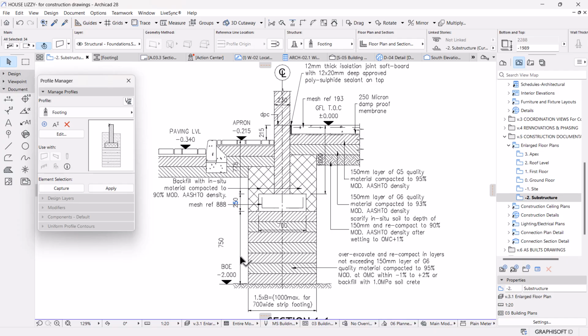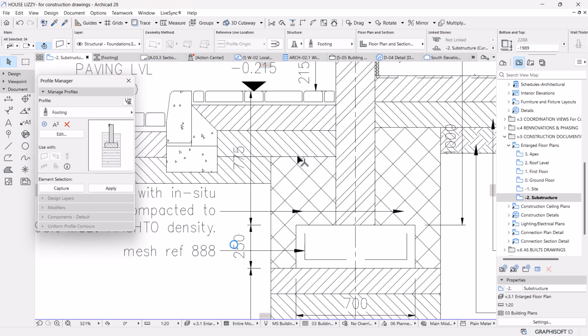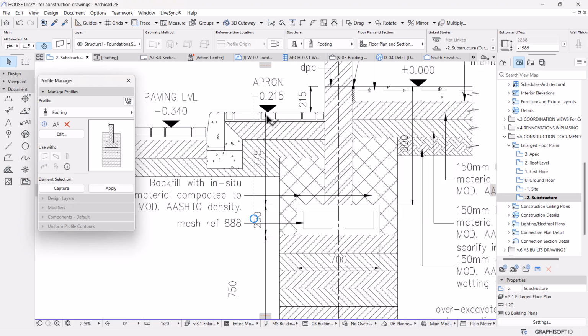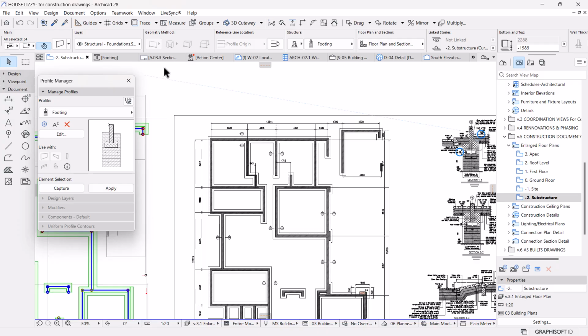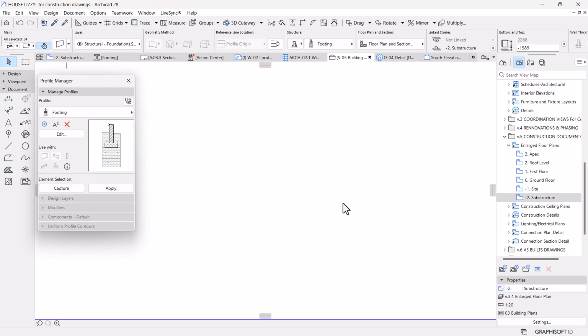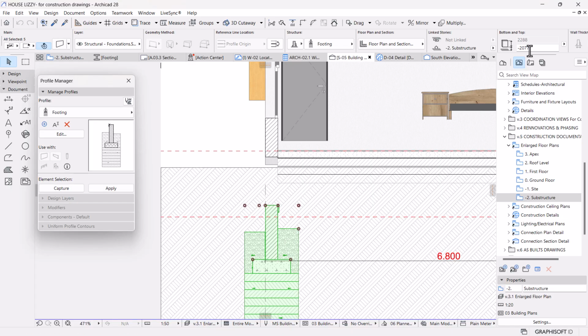Okay, there's excavation depth as well, and then there's 7075 or 775, which is top of apron, and then from concrete footing to floor finish is 1000. That's what he said, but this is what I'm trying to do. So if I had to select this and make it substructure, maybe make it 0, because I've referenced it with the origin point.